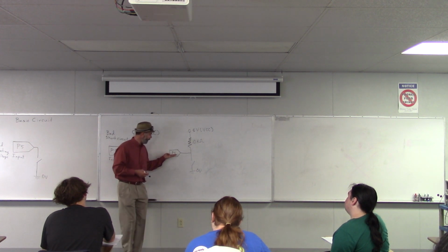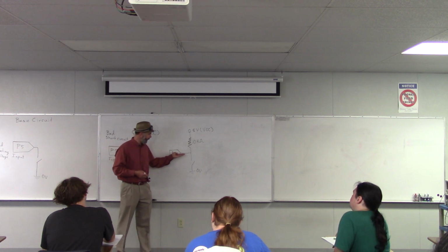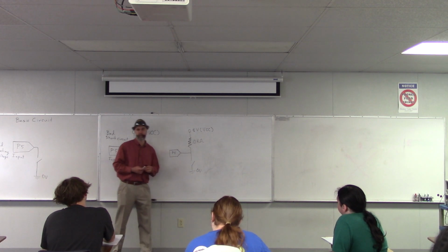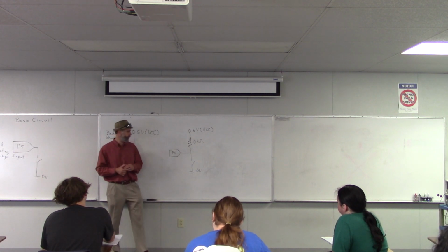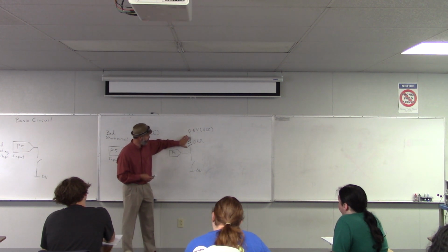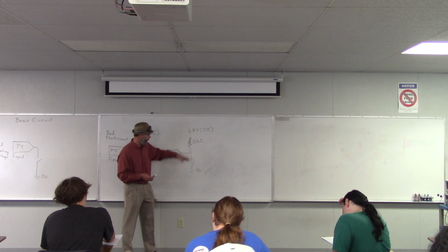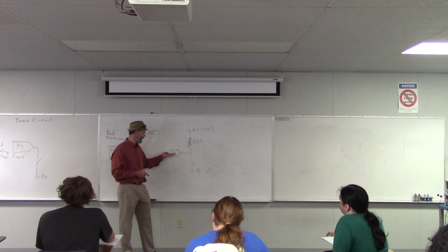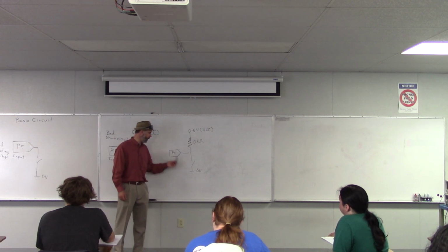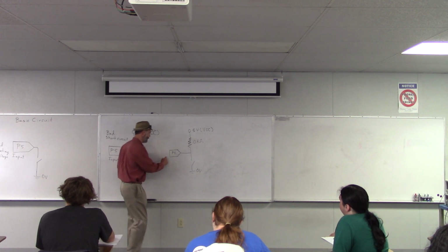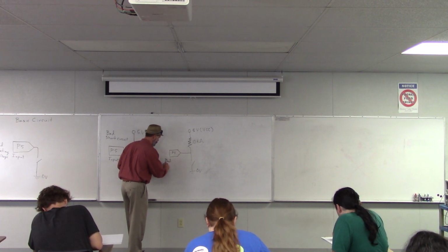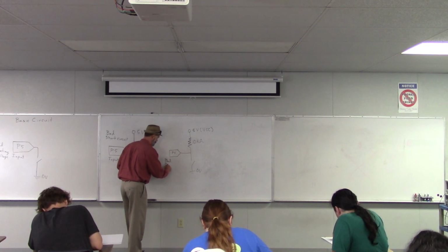Now you've got 5 volts coming out here, connected directly to 0 volts. So what do we call that again? Short circuit. So now, again, you're creating damage, not to the power supply this time, because we've got this resistor between the power supply and ground, but now you would damage or destroy this pin, because too much power would be coming from this pin. You'd have a short circuit. So this one is also bad, because you could have a pin short circuit.